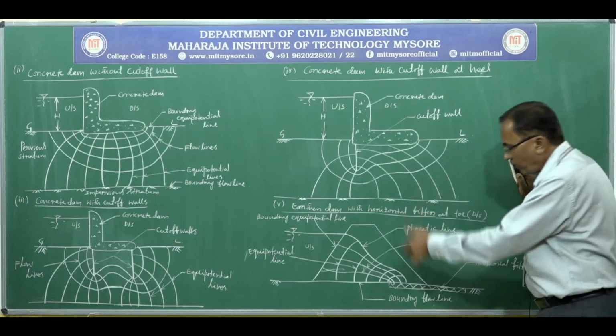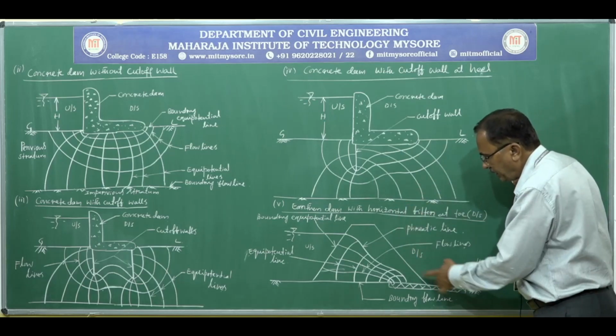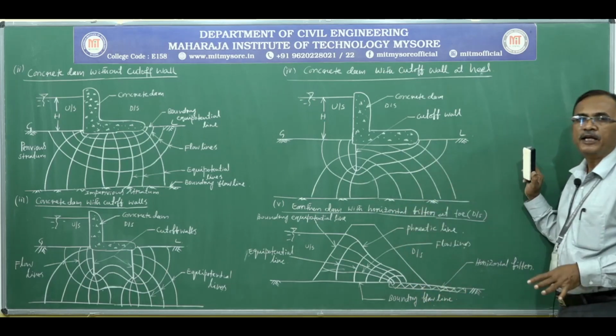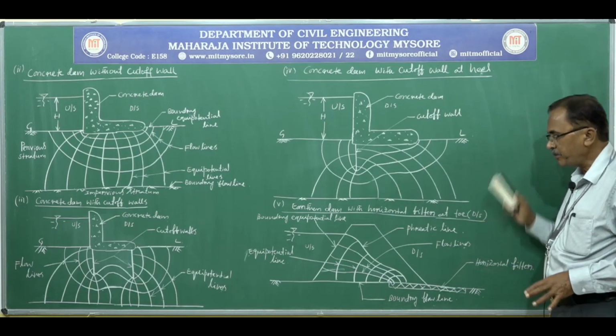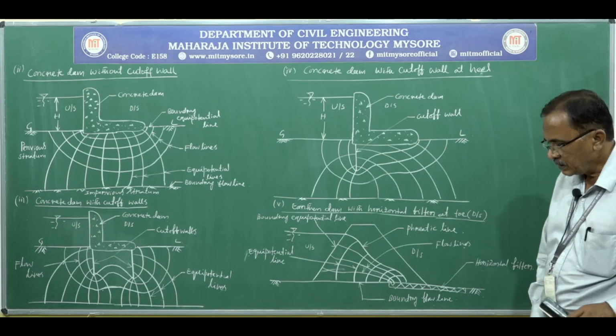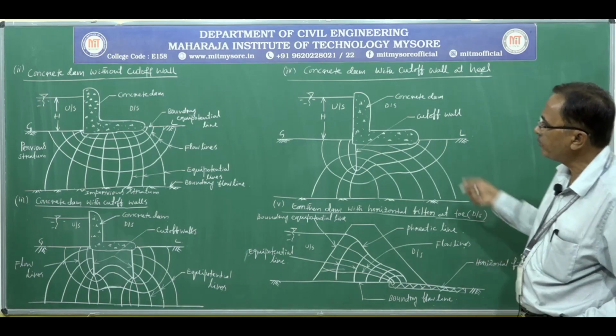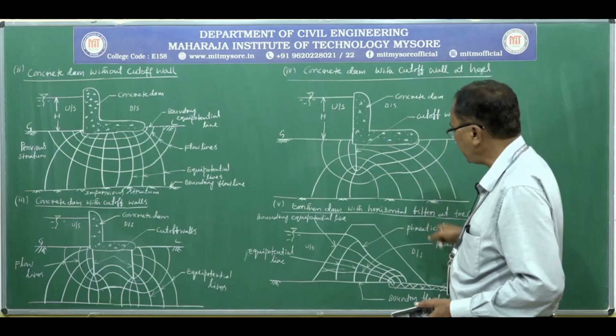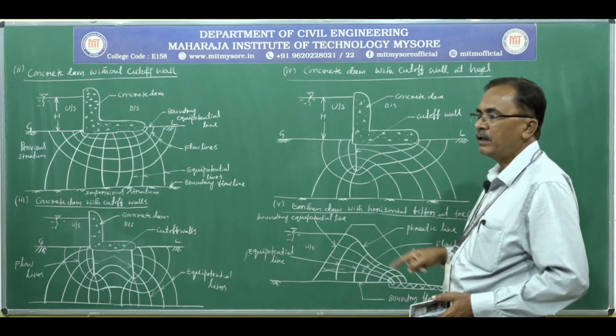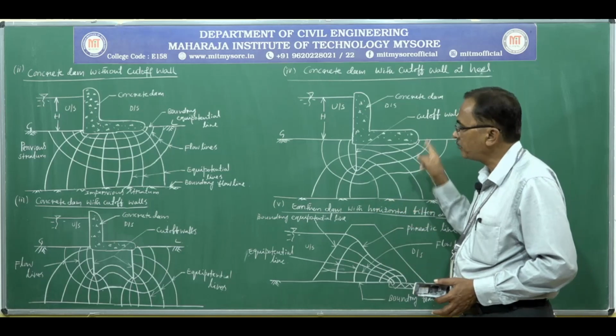There shall be free flow of water in the filter, and there shall not be any building up of hydrostatic pressure or pore pressure, from the safety point of view. So like this you can draw the flow net, flow lines and equipotential lines. These are all the typical flow nets.